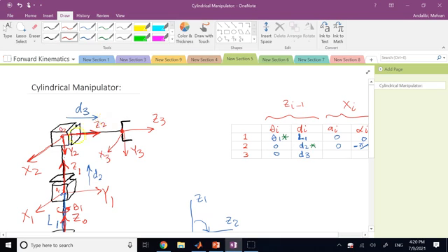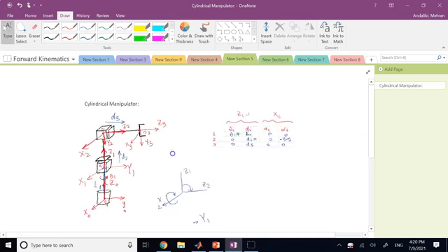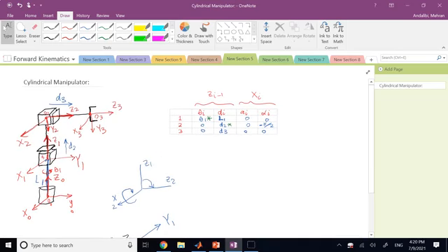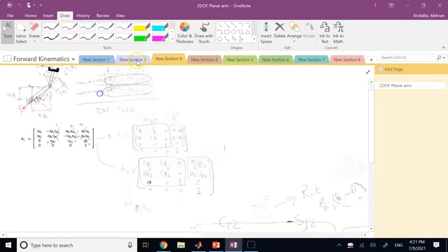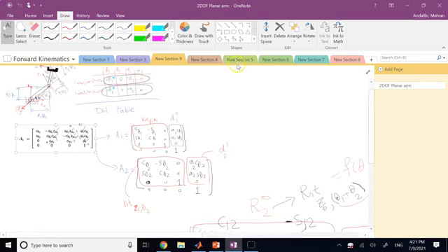Good, so clearly now if I'm able physically to make this distance 0, that means I can completely use D3 to go from O2 to O3, good. Now, do I also need to move along X3? No, no displacement is needed anymore. And is there any twist? Do I need to rotate about X3 to align Z2 and Z3? No, they're already aligned, so no twist is needed. So that is my DH table. It is all set. And now I can go ahead and form those A matrices. And again, if you want, I can bring that formula for it, which I guess it was this guy. Let's bring that in.